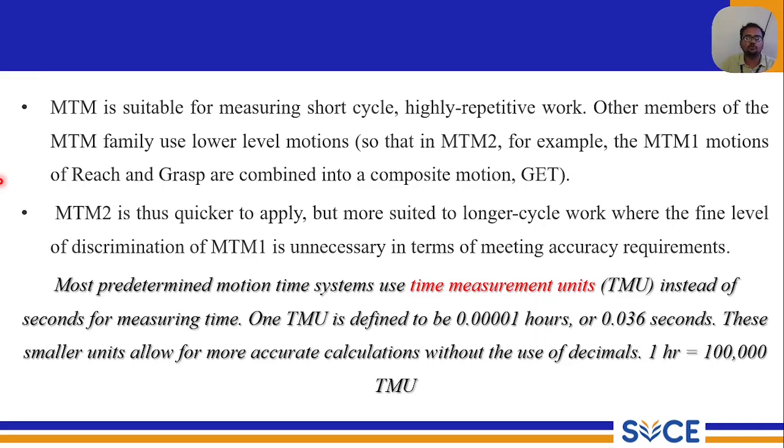To put it together in a nutshell, we have seen many time study and work measurement techniques used in industries for measuring the process as well as the movement of the worker. An ideal method study should improve both the worker and the process, since it tries to eliminate all the unnecessary movement of the worker and all the unnecessary processes carried out. We have been seeing worker-specific time study and work measurement techniques through MTM and micro motion studies. All those recording techniques help improve the workers' efficiency by reducing their fatigue, and provide an overall pleasant environment for the worker to do their activity.